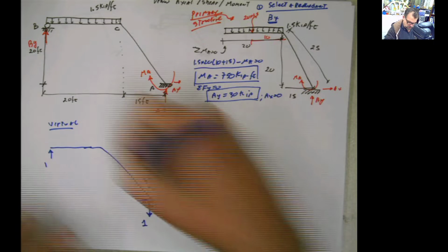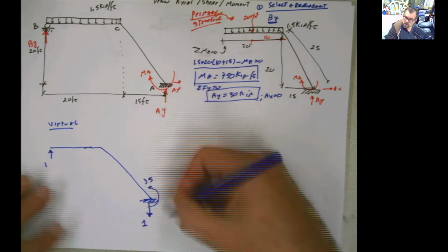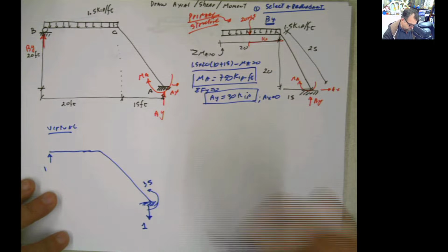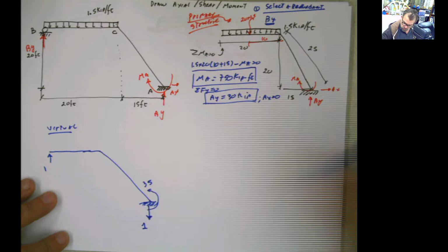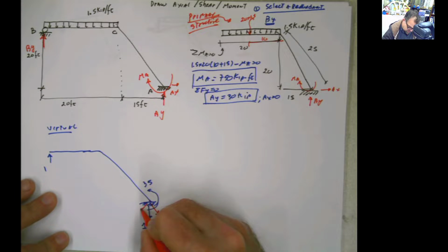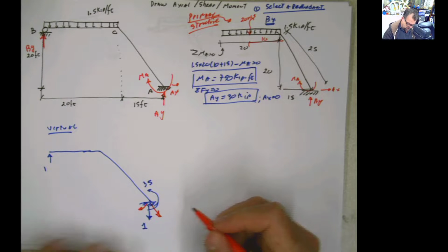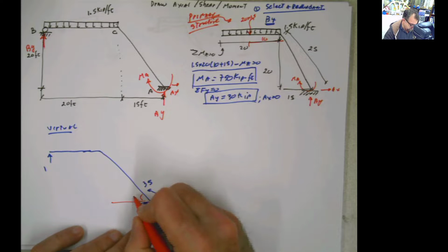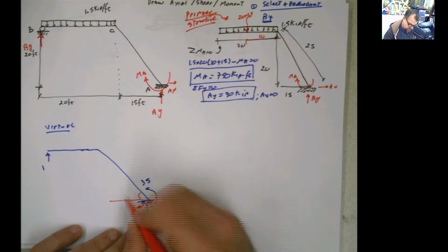I know that I'm going to need my reactions in this local coordinate system, so I better convert that into 2 reactions here. This one here in this direction, and this one here in this direction. And if this is 1, I know this angle here. That angle there is going to be 53.13 degrees.